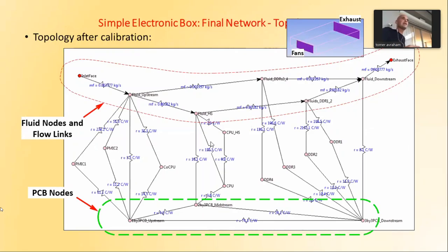You have many ways to do that, actually. You have many laws that say if you had a pipe, then you have system pressure drops. Usually the pressure goes like the mass flow, the volume flow rate squared.